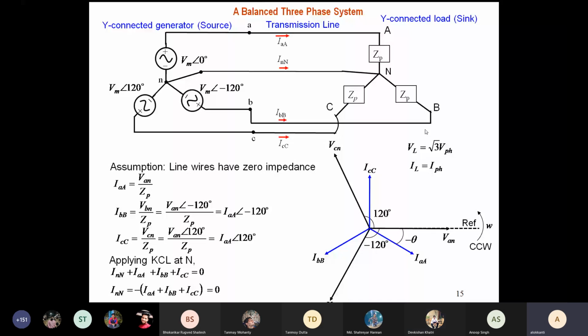So suppose this is the question given to you: a balanced three-phase Y-connected load. The VL is given as 300 volts RMS. The load power is 1200 watts at 0.8 power factor lead. The load is a leading load. Find the line current and per phase load voltages.